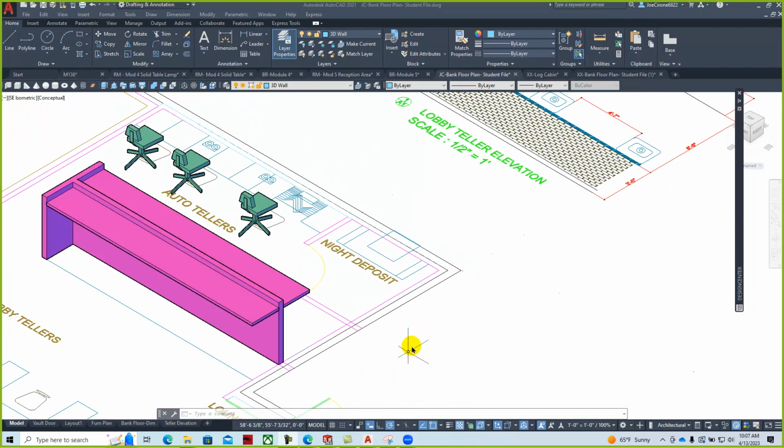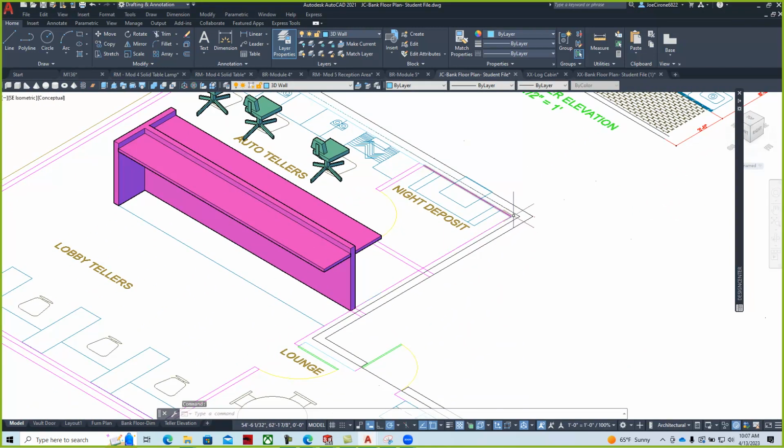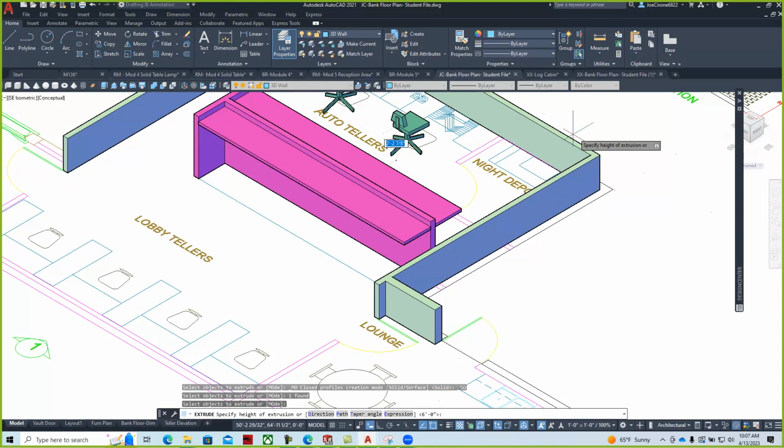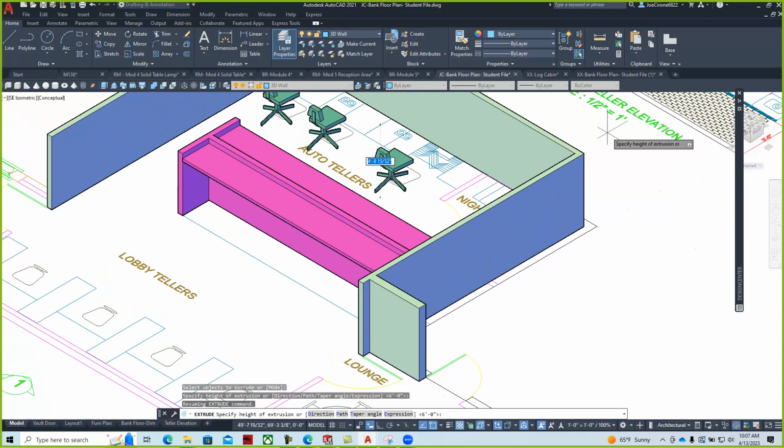Okay, resuming. I had what they call a self-intersection area here, and so I just went through and made the boundary shape. Now, you could convert an existing line by saying p-edit and join. It might be a little bit faster, but we'll extrude. We'll select that line geometry, hit enter, and bring that up. I'm going to make this 6 feet in height, so we'll say 6 feet, enter.